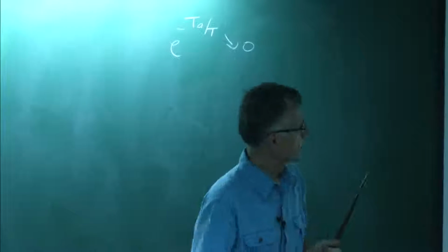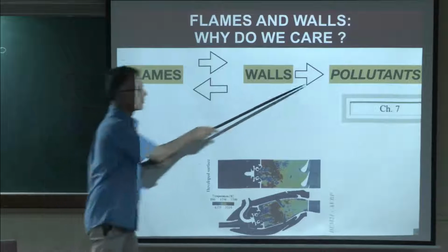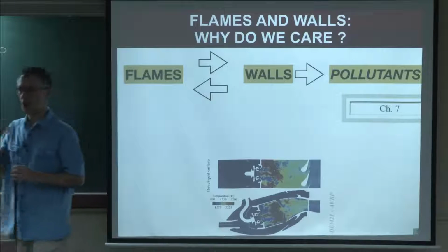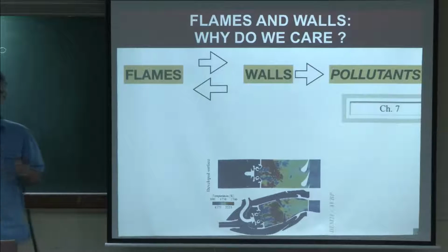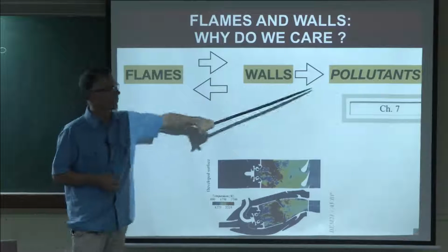Now, this is also a problem for pollution, because if you quench the flame near the wall, the fuel there will not finish burning, so you will start producing unburned hydrocarbons when you open the valves, for example, in an engine.